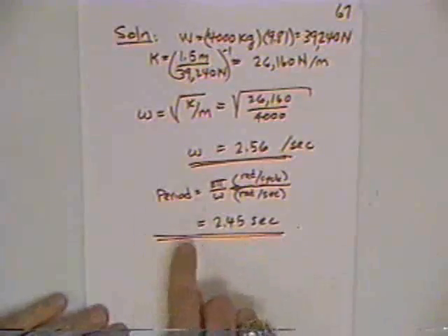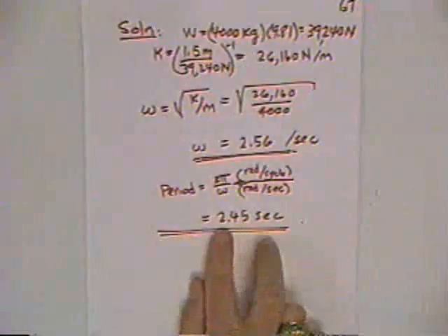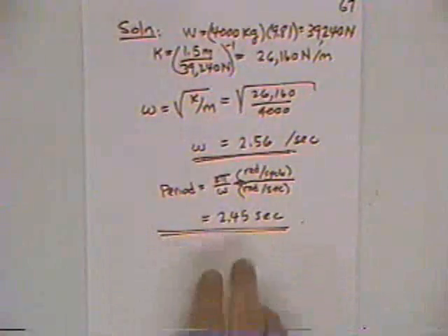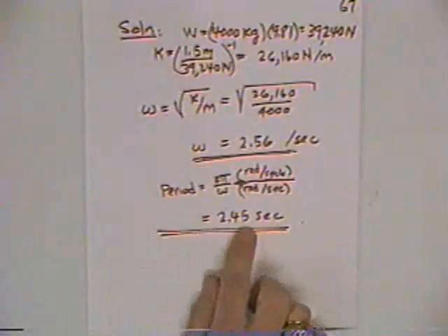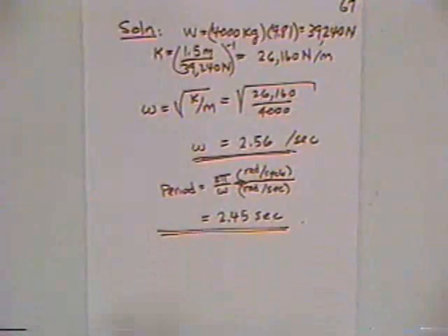And industrial engineers will tell you that vibrations in a certain range are very uncomfortable, and I don't know if this happens to be in that range, but this might be one of those. It would also be important to know if there's some other equipment, maybe the mechanism that starts the lift of the cable, that is applied in such a way that it excites this natural frequency, then you're going to have forced vibration.